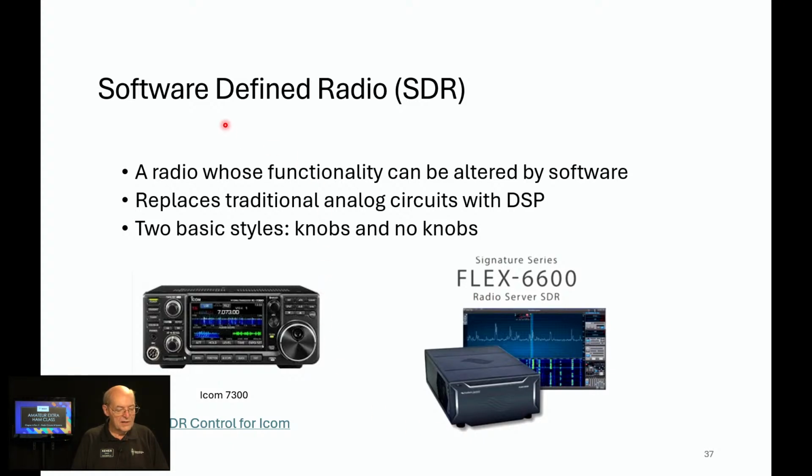So an SDR is a radio whose functionality can be altered by software. That's pretty cool because new features can be added to the radio without changing hardware or adding hardware modules. It replaces traditional analog circuits with digital signal processing. And we talked about knobs and no knobs.